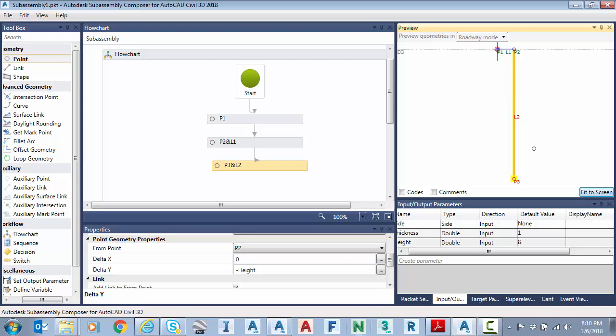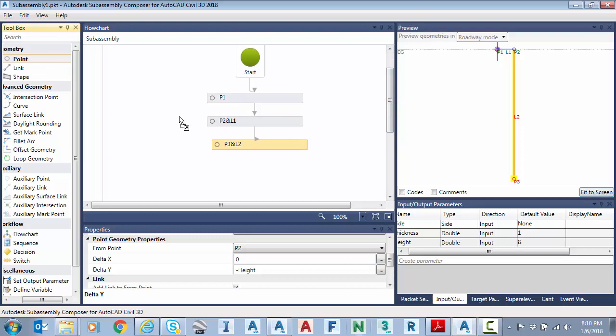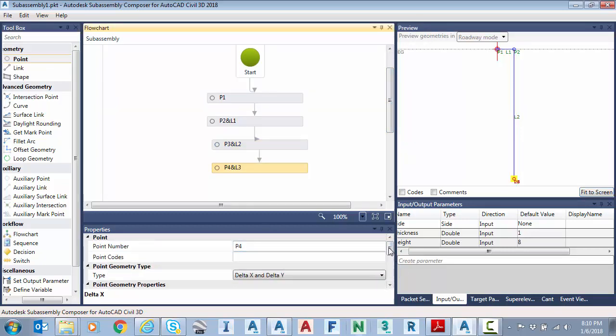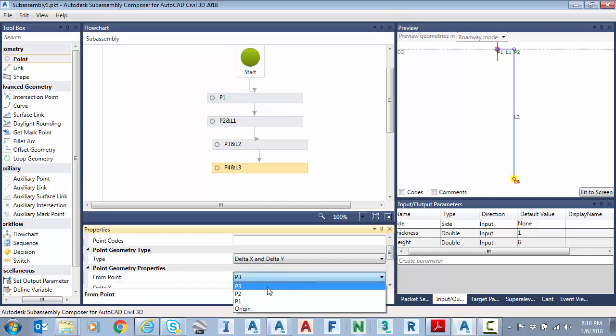But as I mentioned before, many times you'll get in a situation where I'm not able to define the next piece of geometry, and I have to come back to the starting point and go the other way. And really, it would be easier to do that in this case, instead of trying to compute the value of the width of the footer from here. So I'm going to place another point, but now instead of the default, it's relative to 0.3. I'm going to change that to 0.1.